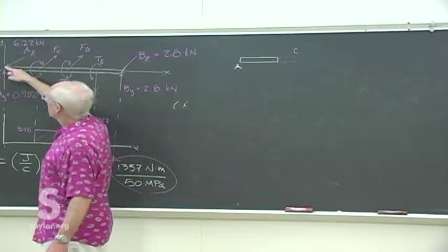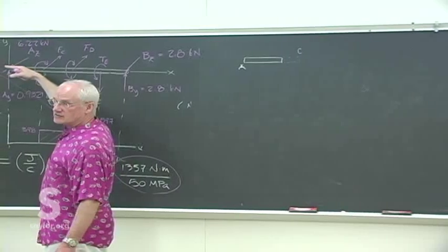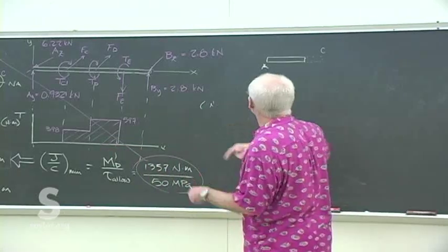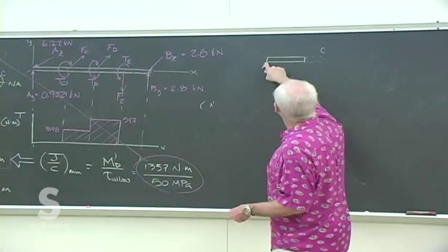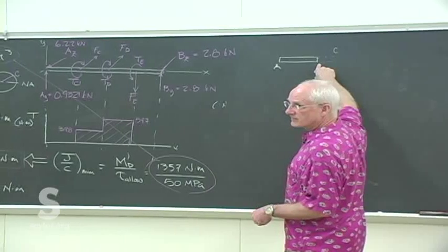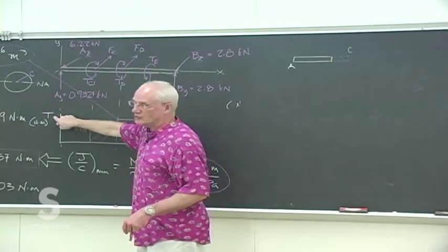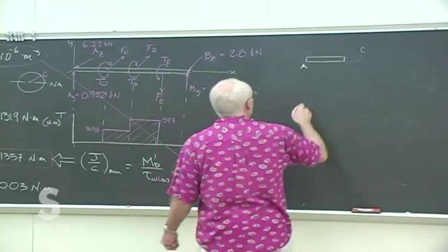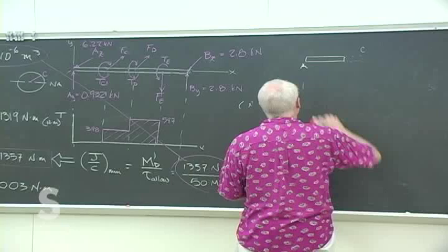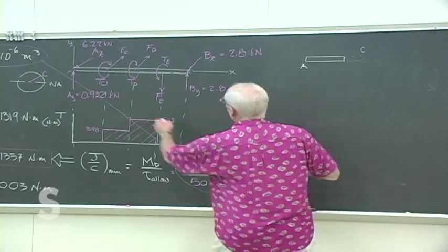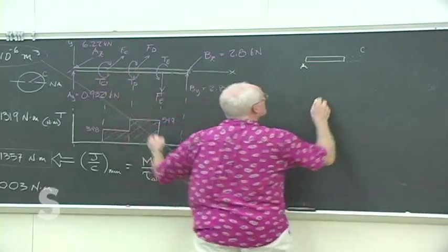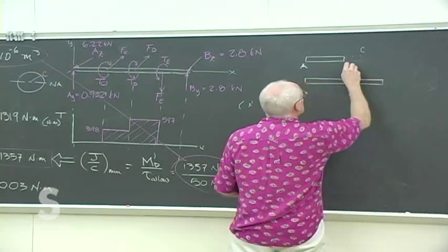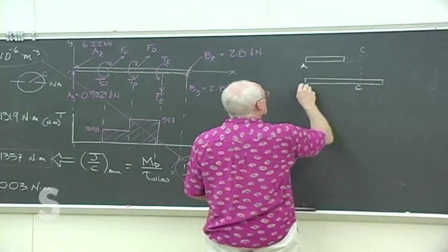This journal bearing is just a freely spinning bearing. It keeps the shaft from flying around and just supports it, but it doesn't apply any torque. So we know between A and C there is no internal torsion. Then we take it a step farther, go past C, but not up to D yet, and put our imaginary cut. So C is right here, A is right there,